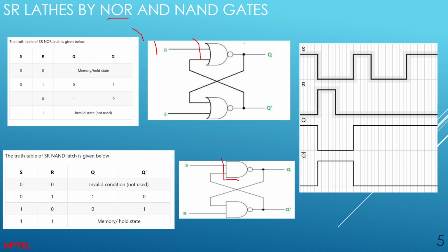So what will be the difference between these? The difference is basically the Q, the output. You have this S and R input, and you can see that instead of 0 1, it is giving 1 0. Please don't learn this table by heart. Instead, you can do the calculation at the examination; it's a simple table, you can work it out.